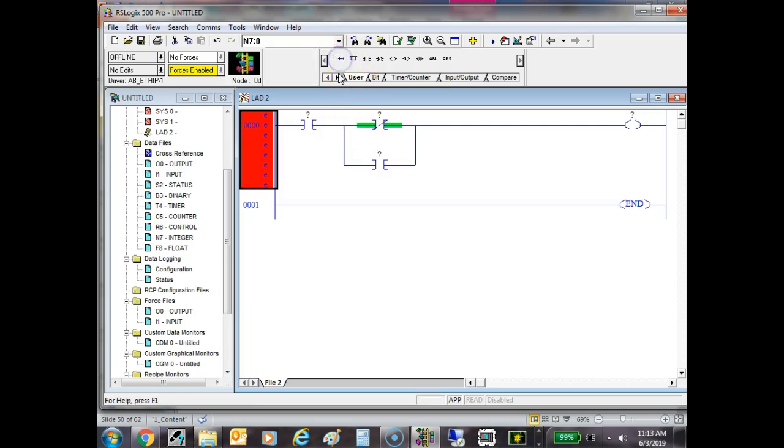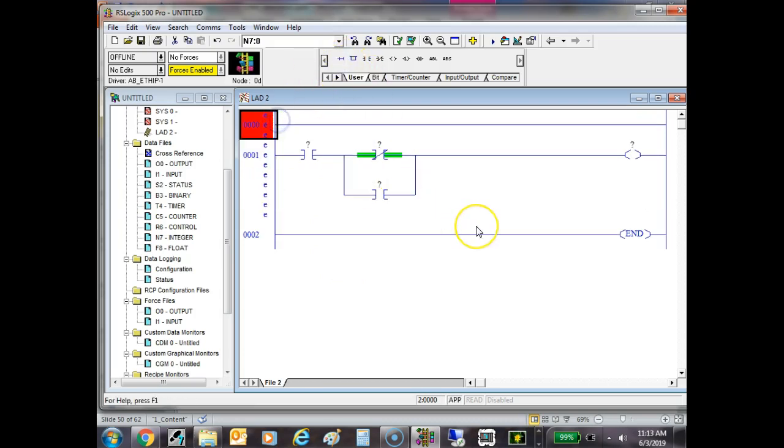And here I can come up and insert another rung. I'll try to, oops. So I've added another rung, right? Well, what we would do on that handheld programmer is we'd have a key that allowed me to do this. Of course, this rung's definitely got a problem because it's going between L1 and L2. That's a short circuit, right? So you won't be able to clear that. See the question mark up there? It's asking for something. I'm not giving it what it needs. And we'll show you that.